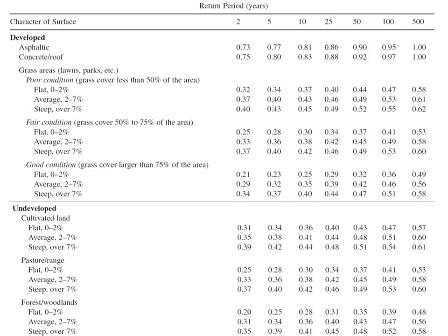And so the best way to pick a good C value is to calibrate the model. It's to go to a parking lot somewhere and measure the rainfall intensity and measure the water coming off the parking lot. So you have quantified in our Q equals CIA. If you went to a parking lot and you measured the Q and you measured the A and you measured the I, then that's the best way to get a C value. It's not to just look it up off of a table. It's to go to an area and actually calibrate what the C value is for the type of surface or the type of land area that you're interested in.